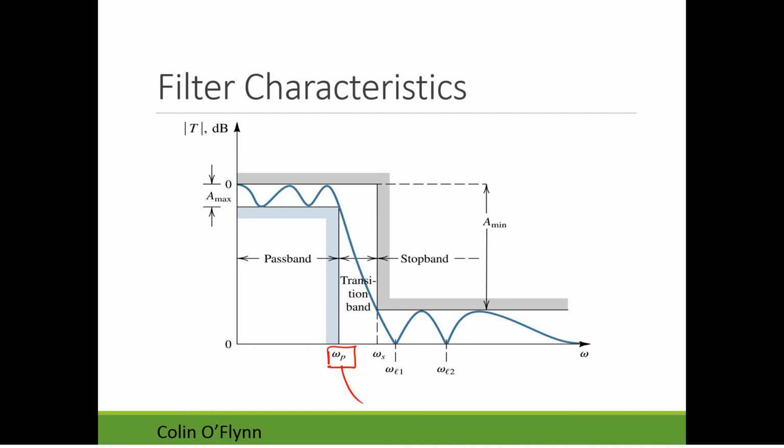So we have what's called the pass band. This is for a low pass filter, but you should get the idea of the notation. The pass band is the frequencies where signals are allowed. If the signal is within this frequency range, it passes through the filter without being attenuated. The other axis here, you can consider it gain or attenuation. As it goes negative, it means it's attenuating those signals more in those certain frequency bands.